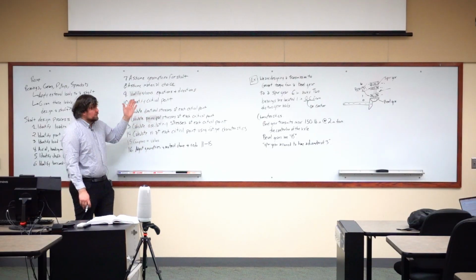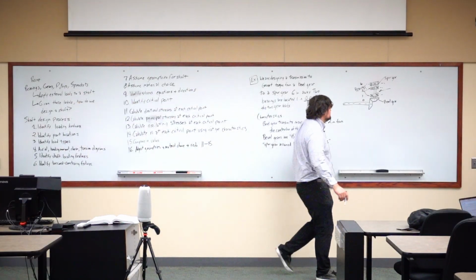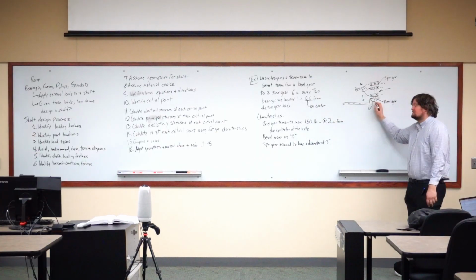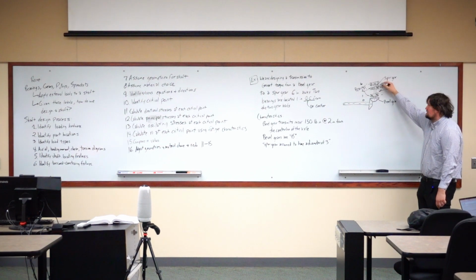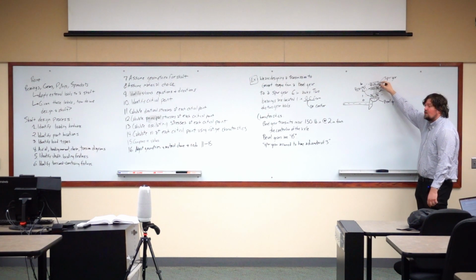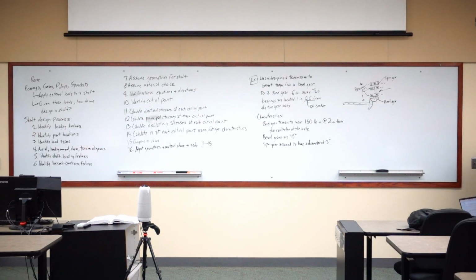Okay. We are going to have to make this bigger than 6 inches just because 6 inches is the location of the center line of this load to the location of the center line of this load. If we only had our shaft be 6 inches, we would have nothing holding these two gears in place. Now for one of those, that's actually fine.